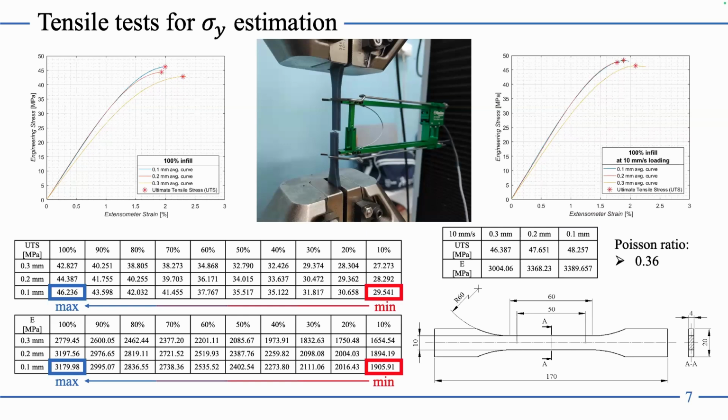The elastic modulus goes from about 2 gigapascals to 3 depending on the infill density. Okay, I'm showing just this. We'll use these results for material modeling, like the professor from Brescia in calibration. So you'll need some data with different strain rates to acquire a proper model.